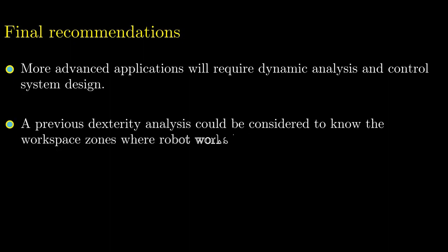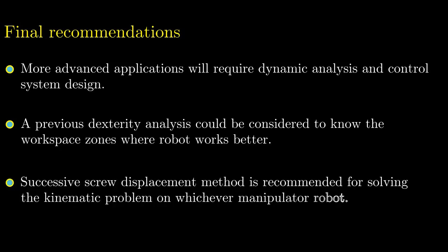Second, for efficient tracking of reference trajectories, a previous dexterity analysis must be considered to know the workspace zones where the robot works better. And finally, the inverse kinematic equations were obtained from the successive screw displacement method previously used as another representation in the forward kinematics. In general, I would recommend this method for solving the kinematic problem on any manipulator robot.